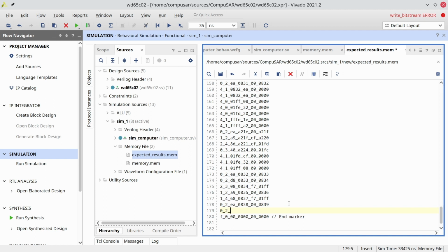So, going back to the end of the file, we want to add an implied addressing mode that takes 2 cycles. The opcode is 18, which is clear carry. It's going to be read from 0839. Since this is an implied, we do not tell it what value it needs to do on the last cycle. It doesn't matter. And the last access will be to the next address where the next instruction is going to be read, because the instruction takes 2 cycles and it doesn't do anything interesting with the memory on its second cycle. Let's also say that this is the ROL test.